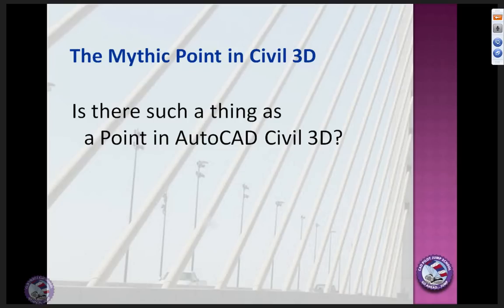So the key issue here is Civil 3D is data centric. What you see on your screen is just the output of a whole bunch of style processes working to show you something that looks like something on your screen. The data is the underlying thing that is most important in Civil 3D, and keeping that, managing that, and handling that is very different than an old AutoCAD-based piece of software like Eagle Point, or some things that actually run inside Civil 3D now, like Carlson. There, the point is an individual thing. Inside Civil 3D, it's really data being shown as something on your screen.